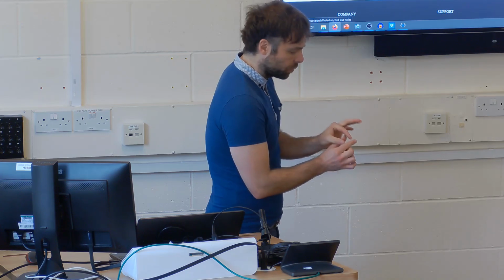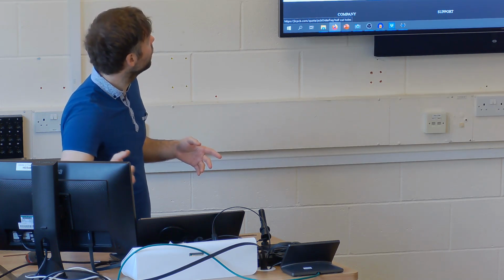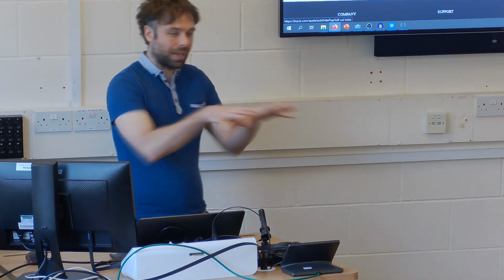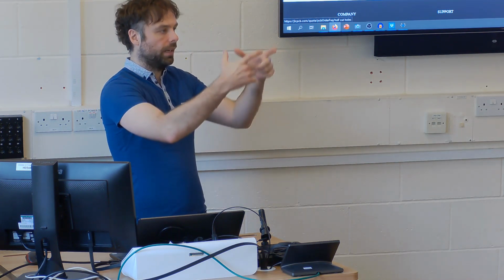Castellated holes. That's when you've got a PCB, like imagine you've got a small daughter board PCB that you've designed, like it's got a Raspberry Pi or something on it. If you want to connect that to another larger PCB, you can use these castellated holes, and then you just put a surface mount pad on the motherboard PCB, and then you put the castellated hole daughter board on top of that, and you just solder. You just put chunks of solder along those edges, and the solder wicks up. Do you know what I mean? Does that make sense? Yeah. It's almost like a through hole in one board, and it absorbs up into it and solders it together. Yeah, apart from the through holes chopped in half. Okay.